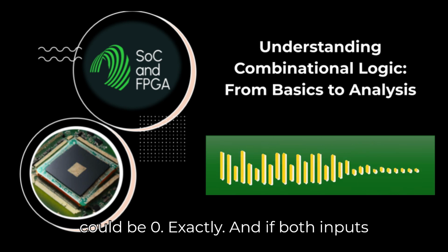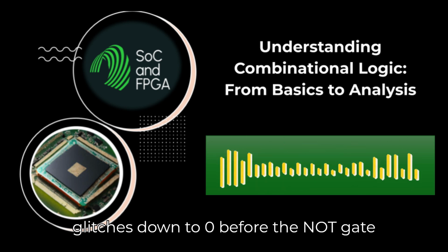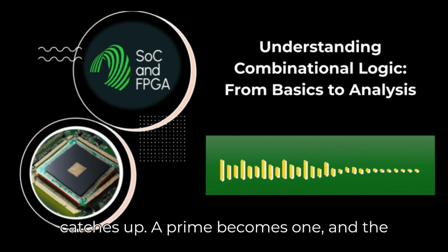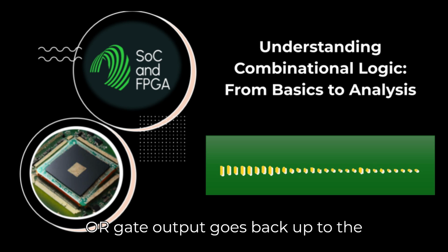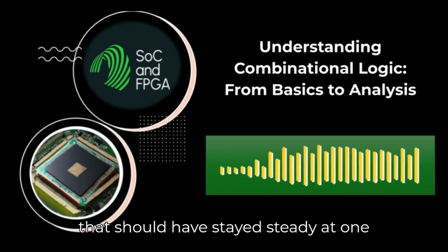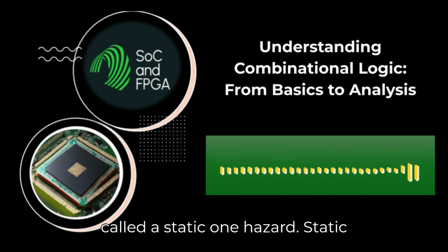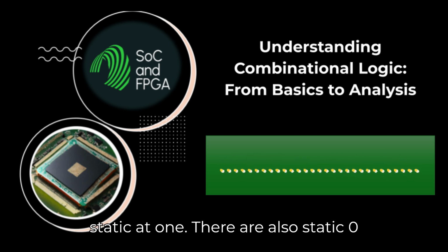Exactly. And if both inputs are 0, the OR gate's output momentarily glitches down to 0 before the NOT gate catches up, A prime becomes 1, and the OR gate output goes back up to the correct value of 1. Wow. So the output that should have stayed steady at 1 dipped down to 0 for a moment. That's called a static 1 hazard. Static because the output should have stayed static at 1.